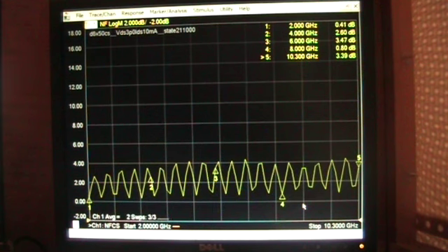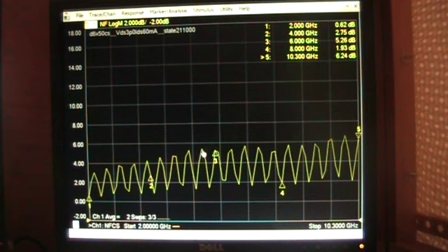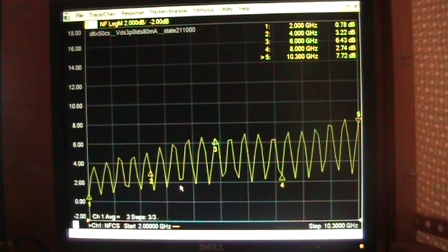There we go. Now we have a very high gamma, so we're actually rotating around more or less the outside of the Smith chart, and you can see that we are still occasionally getting close to a minima, these lowest points on the chart. But when we wrap around, we're very, very far away from F-min, and we see more noise figure. So what this tells us is that we're slowly working our way around different positions on the Smith chart to capture noise figure.